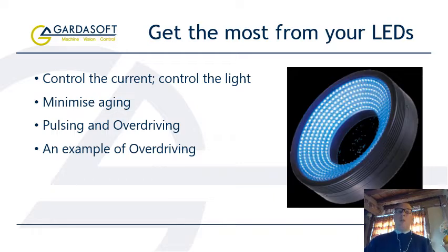Pulsing the light also allows the image capture of objects moving at high speed without image blur, as I mentioned earlier. Gardasoft controllers have fine adjustment of pulse timing, which is often more accurate than the camera's internal timing. While overdriving is a very powerful technique, it is necessary to ensure the LED is not driven at too high a current for too long, which may damage the light.